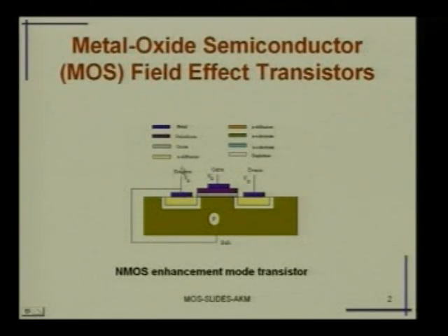So, we will have a source terminal, which is a metal, a drain terminal, again another metal terminal, and the gate. Lastly, the substrate is also usually connected to the source, but you can give it a bias; later in some circuits we will see that we can bias the substrate as the fourth terminal. So, now what happens, you have seen that this is a typical NMOS transistor.